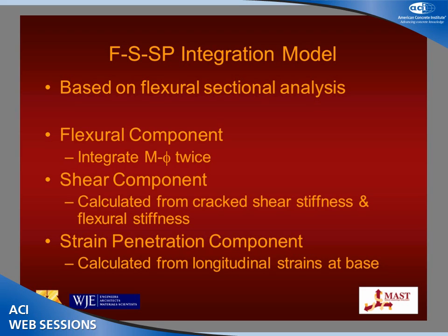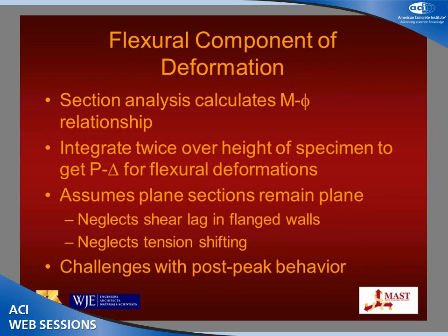From that, you've got your flexural component of deformation, which you get from integrating your moment curvature twice. The shear component is calculated from crack shear stiffness and flexural stiffness, and then the strain penetration component is calculated from the longitudinal strains at the base. So for the flexural component, take your section analysis and calculate your moment curvature relationship. Integrate it twice. That's pretty easy, pretty straightforward.